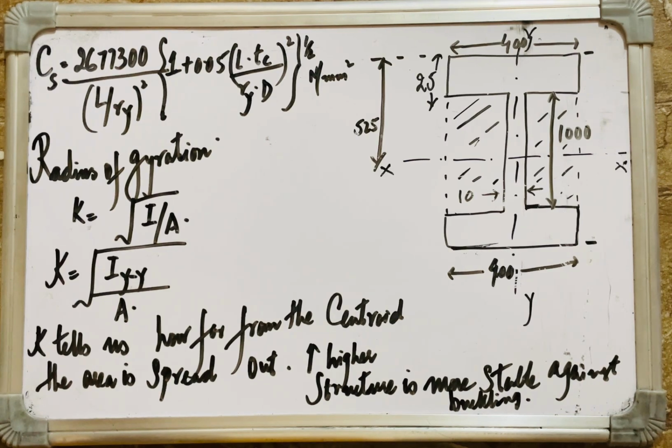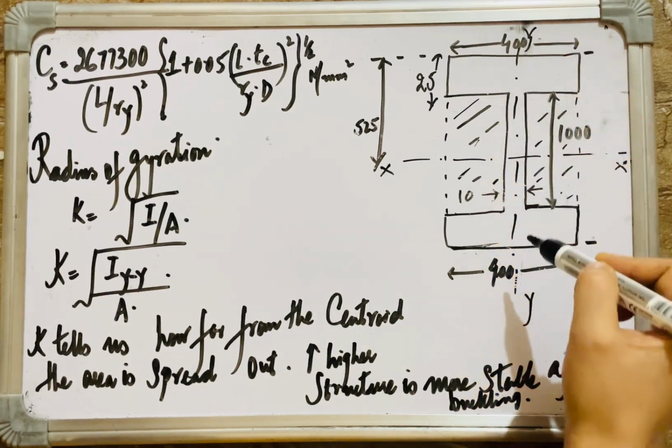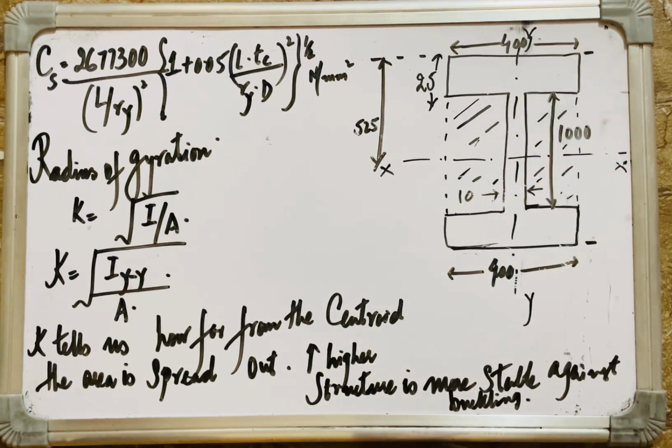The axis you use for calculating radius of gyration depends on which axis you're analyzing the object's rotation or bending about. The stability analysis about a particular axis demands the moment of inertia from the same axis to calculate the radius of gyration. If I'm calculating radius of gyration about the y-axis, that means this is the axis we are analyzing the object's rotation or bending about, and the stability analysis will be taken from the same axis, the y.